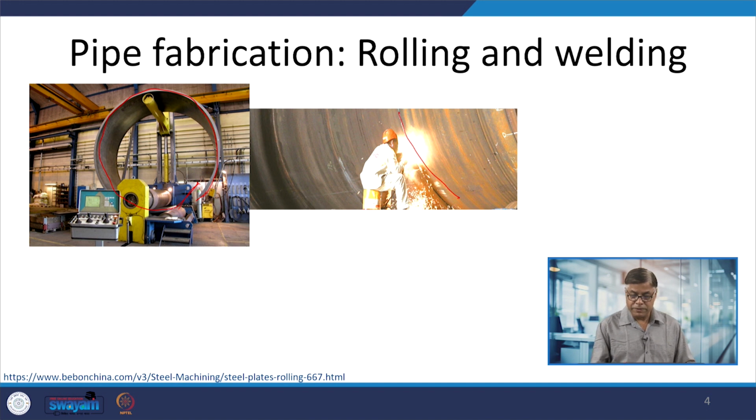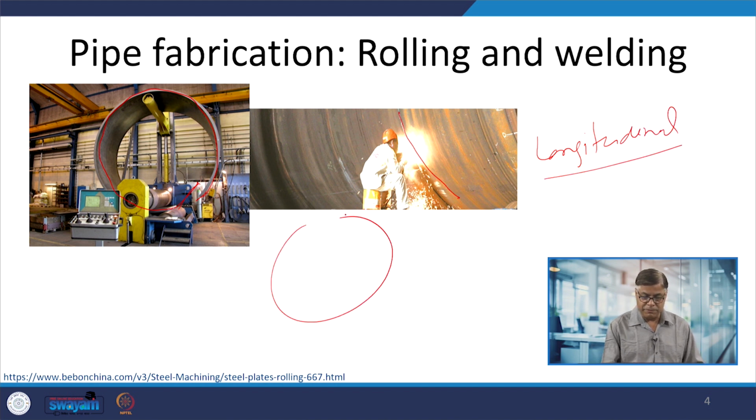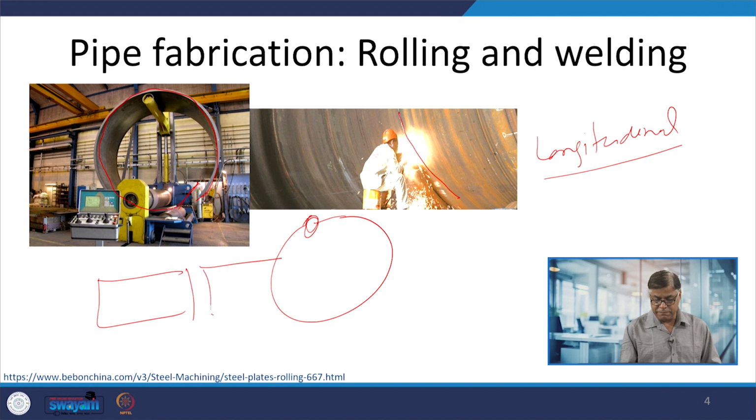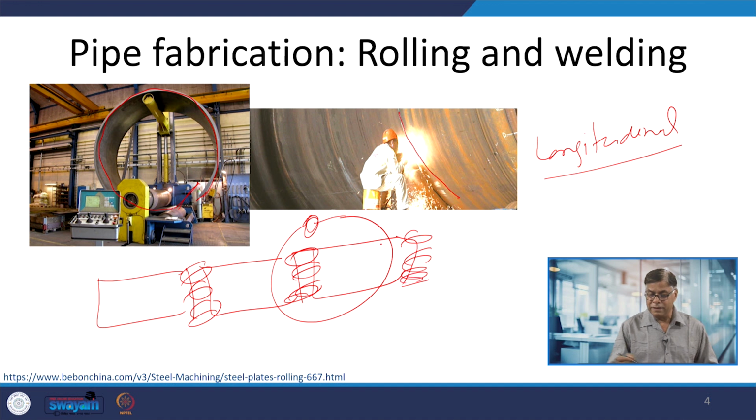Okay. So, there will be two types of welds. One is longitudinal, along the length, because say after deformation we have got it like this, then the weld is to be made all along the length. So, that will be the longitudinal weld, and when there are a number of pipes which have been made, then to obtain the desired length of the pipe in continuity, again the circumferential welds are made. So, the pipes need to be reconnected circumferentially.